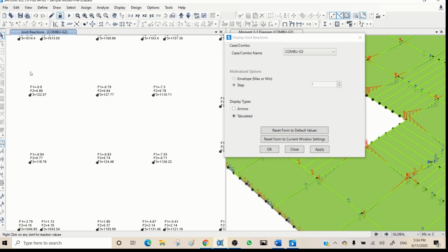Just you need to be mindful that you need to track everything, you need to check everything and show it's correct. We saw this abnormal internal forces in frame, top frame. We realized that this is due to difference in settlement of the foundation around the lift and the lift itself, and now we can clearly see that lift is taking 10% of the load comparing to others. It could be mistake in meshing the foundation, it could be mistake in meshing the wall to transfer load to the wall. We just need to find it.